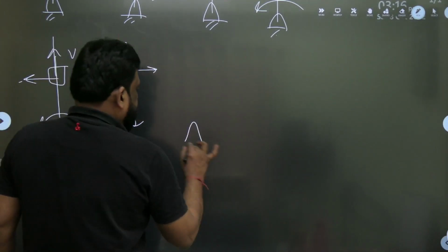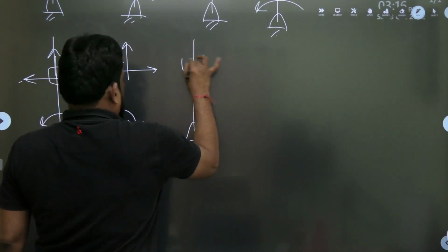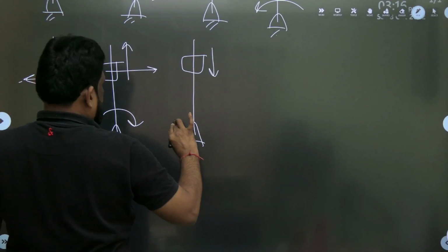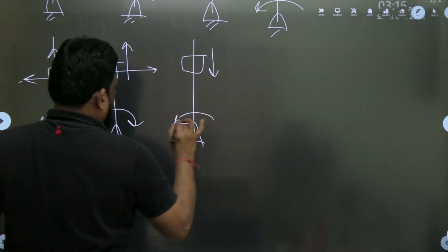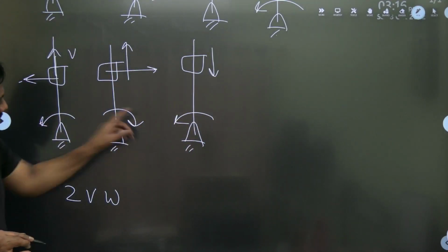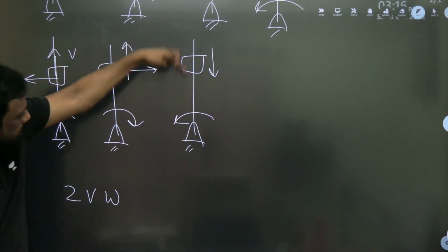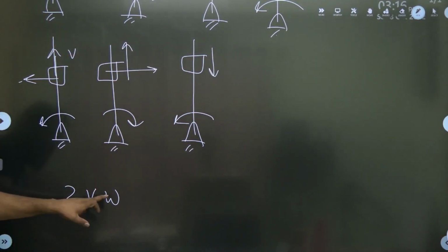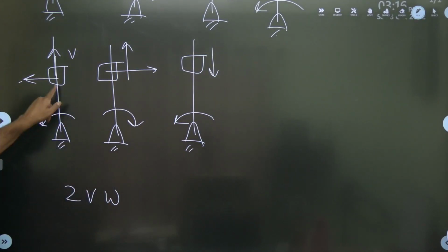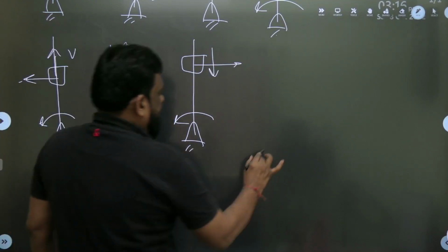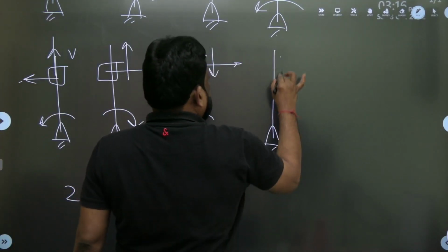Now come here. Let us take downwards and let us take anti-clockwise. Look at, sirs. Anti-clockwise is the same, I am taking it with respect to this. Omega is not changing. V upward, V downward, V is becoming negative. So negative into positive is negative. This is negative, which means with respect to this, it will be negative like this. Coriolis acceleration.